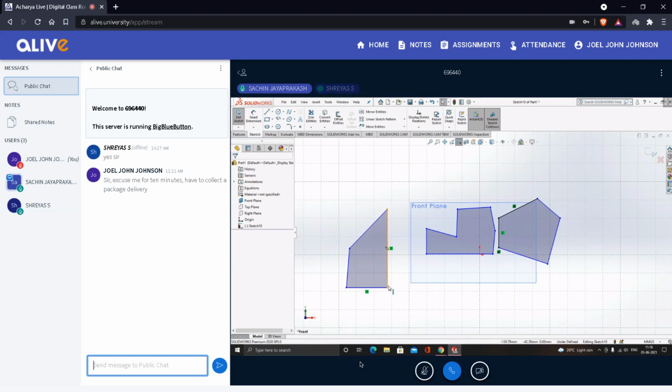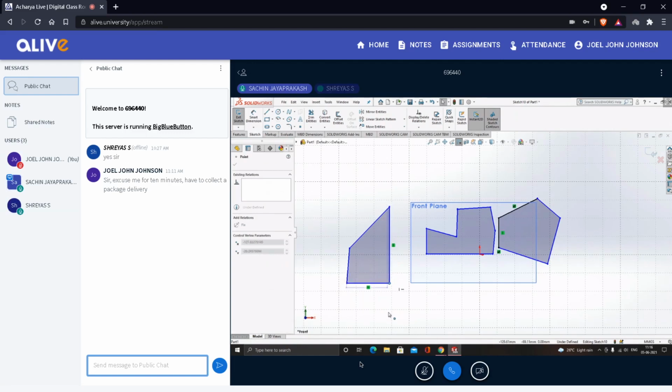Fixed, which means basically there is a constraint. So it will move only in this direction or this. If I select this and try to move, see, I can move like this or this, not vertically. And these two lines also are moving together, because this is the only connection for these two, so it will move like this. But this is free. So this I can move like this, but still this is changing.